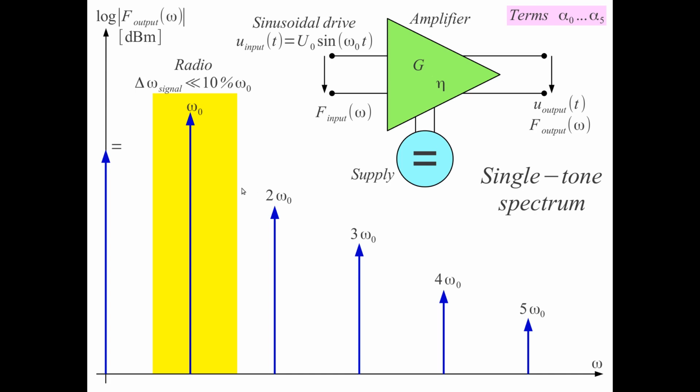So this should really be at the output just a low pass filter to filter out the harmonics, and some AC coupling with a coupling capacitor to remove the DC. So this is very simple to remove here. These unwanted terms are quite simple to remove. So it seems that in radio we are able to handle distortion.